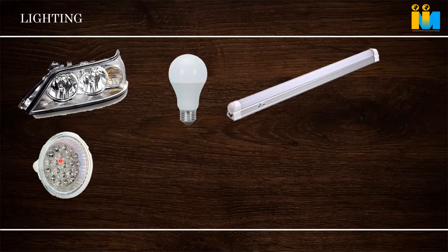Initially the mold will be kept in a slightly open condition. The mold construction is also totally different. It's not a normal mold. It has vertical type of bearings and all. In the slightly open condition, the raw material will be injected into the mold. Once it is injected, the mold closes and compresses the raw material again. Otherwise, this type of thick article cannot be formed, because sink marks and blow holes will come with normal injection. So injection will be done, then the material will be compressed heavily, and this part is made.